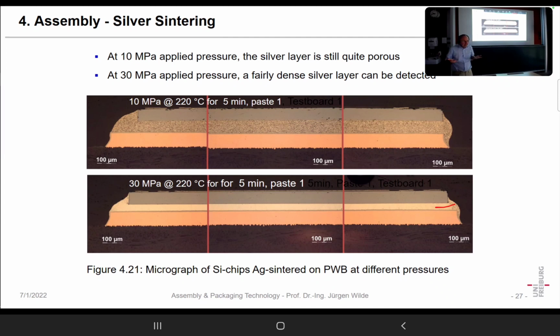The second thing is, silicon has a thermal conductivity of 120 to 150 or so. The solder we have seen has 50. So working on the solder would have much more effect than working on the silicon.